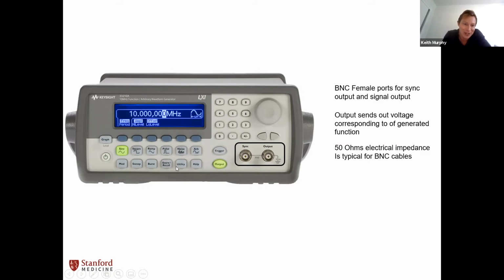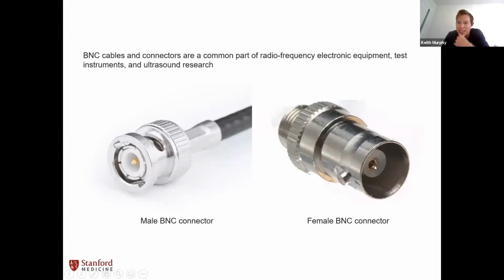So Kim, you were asking also about burst. So I'm glad we've described that. So what about these output channels? Kim, you can correct me if I'm wrong, but I think the origin of this type of output, and these are called BNC connectors. Here you can see, and we'll zoom in to the cable that connects to these, a female BNC connector where it has this input sector, and then the male BNC that has the actual input itself. And you can see these little locking mechanisms, and we'll show you during the class how to connect these, but you essentially slide these rings together and lock them in.